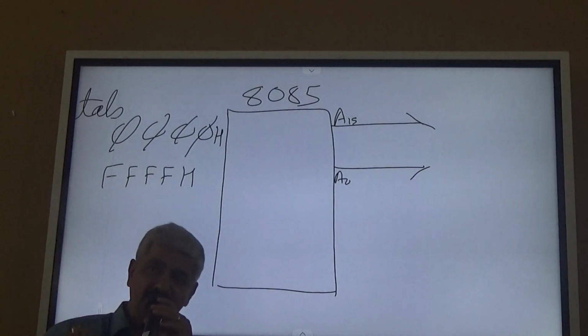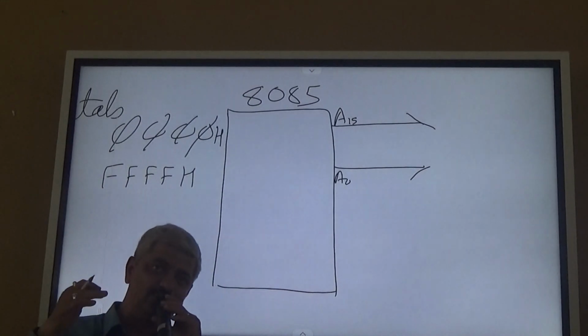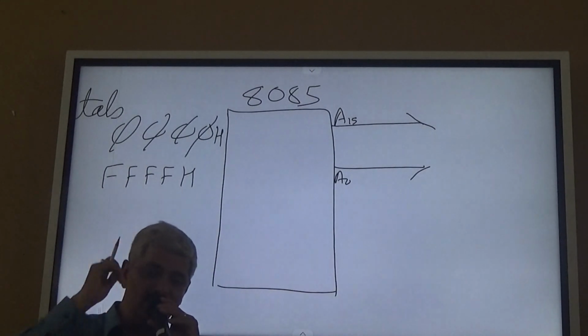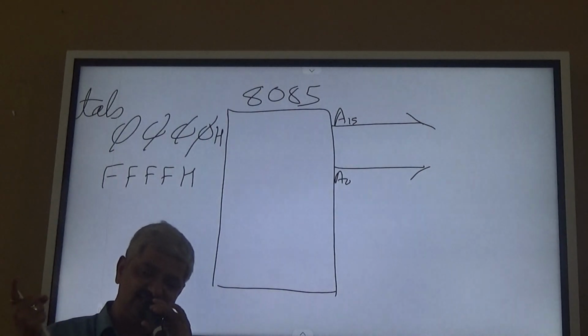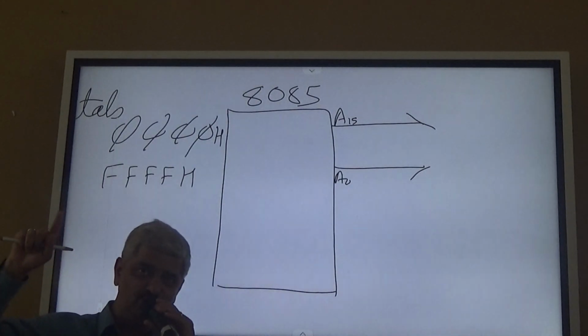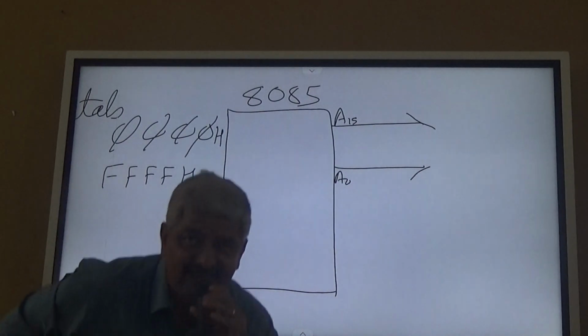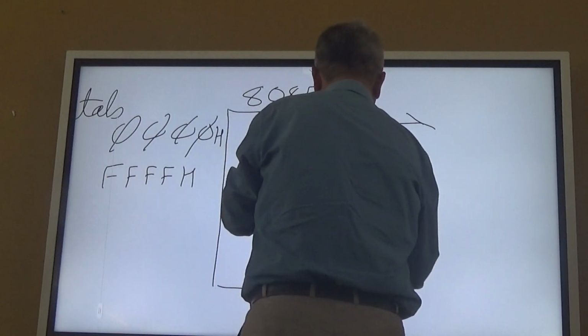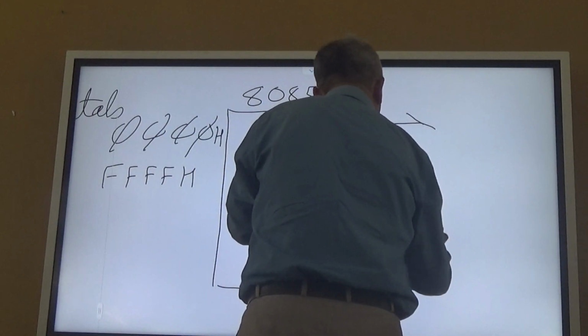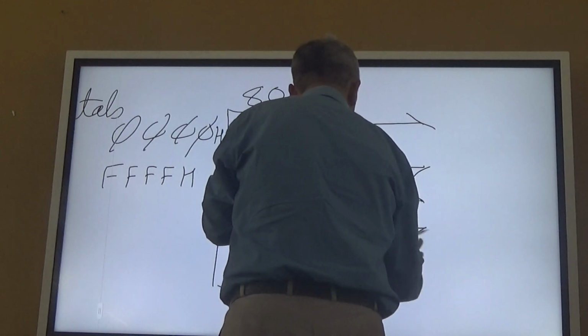Now the microprocessor is connected, as Von Neumann has said, with data lines. So 8085 has 8 data lines, numbered D7 to D0. I again repeat that multiplexing of address and data is not required for this understanding, so I have skipped it and made it simple.